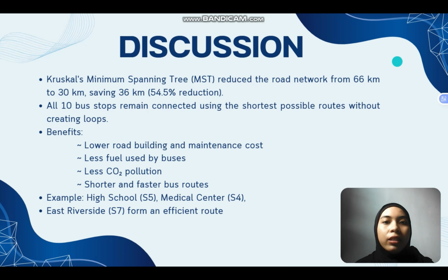Now I will discuss the findings of our study. After applying the Kruskal minimum spanning tree, we successfully reduced the road network from 66 km to 30 km. This means the total distance was reduced by 36 km, which is about a 45.5% reduction. Although the total distance became much shorter, all 10 bus stops remain connected. This is because the algorithm selected only the essential roads and avoided unnecessary loops, making the network more efficient.